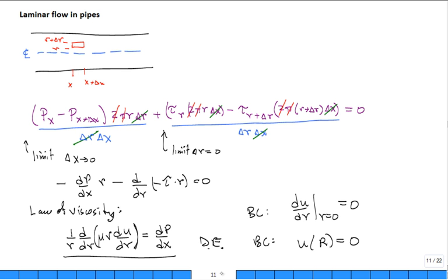Well, let's go ahead and do the derivation for the flow in a laminar pipe. What I did was I wrote this out so I could go a little faster. Basically, it's in every fluid mechanics textbook. So you start and you develop a little differential volume of fluid, and you look at the forces on it. It has pressure at X pushing it in the positive X direction, and pressure at X plus delta X pushing in the negative X direction.